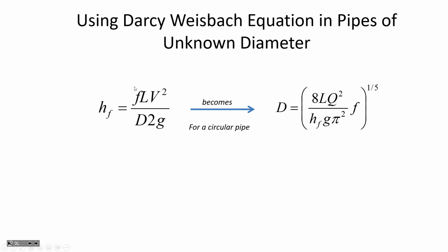If you make the diameter of a pipe smaller, then for a given flow rate, the velocity will be moving more quickly through the pipe. High velocity means high Reynolds number, and therefore a different friction factor applies for the same flow rate and the same pipe material, a different friction factor depending on which diameter you use. So the tricky thing about this whole question of how big the pipe diameter should be is that the f value changes anytime you change the diameter.